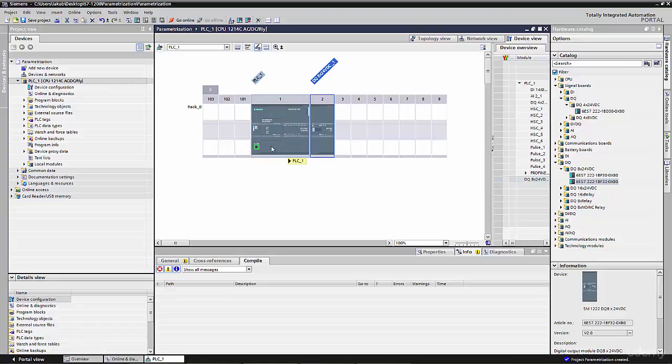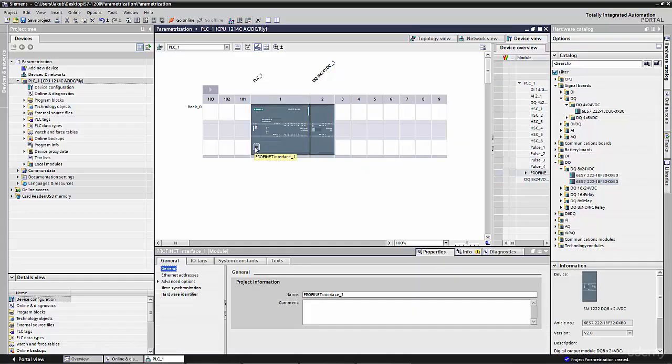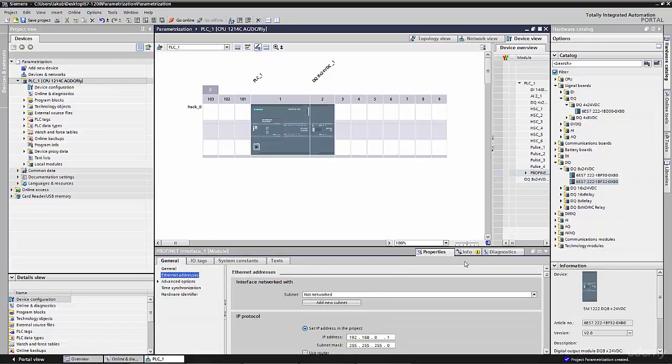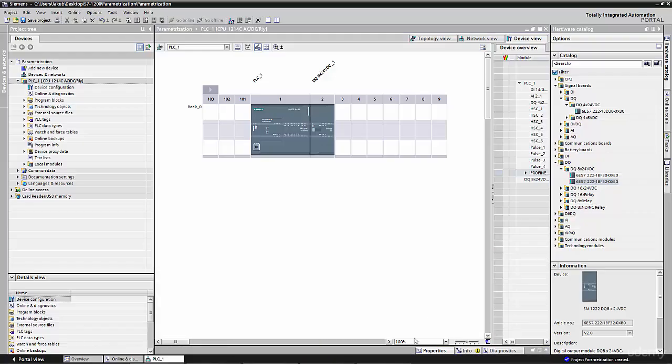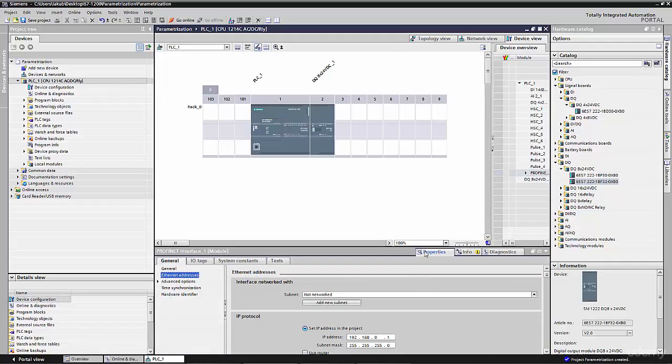The next thing which we have to do when we obtain a new PLC is add a new IP address. We can change this address exactly by clicking this green area. It is the Ethernet address, at the Ethernet socket exactly, and in properties. If you haven't got this properties window, it can sometimes be like this, so only click this arrow up and it opens, and check properties.